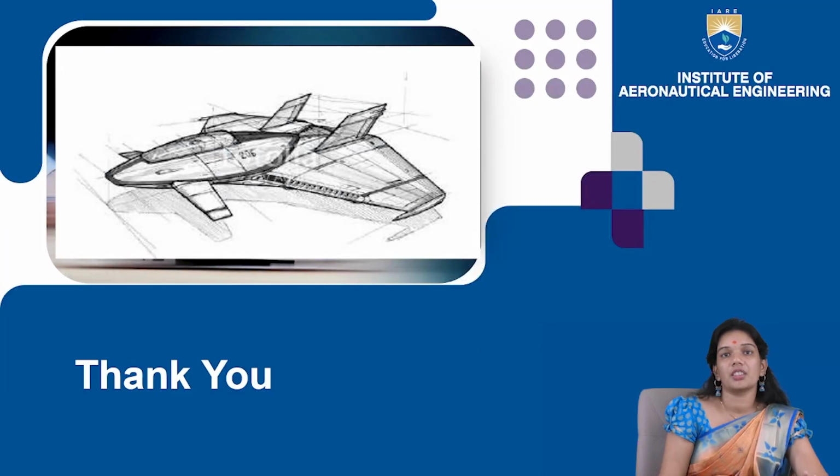All we have seen is the geometrical sizing of a fuselage, a wing, a tail, and finally the control surfaces, right? Control surfaces also have to be sized very well. Then finally it was about lofting, or the conceptual drawing, right? All the analysis, optimization and statistical estimations were done to finally come up to a point of having an initial layout or sketch.